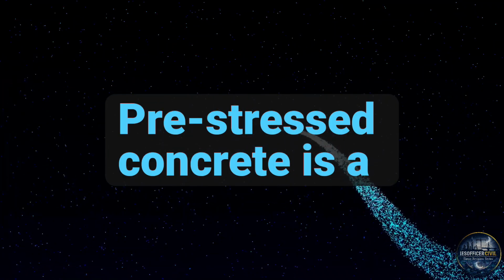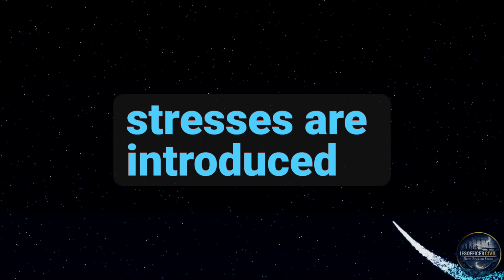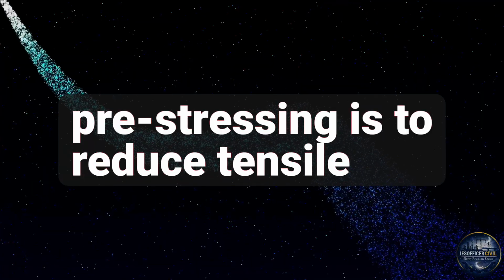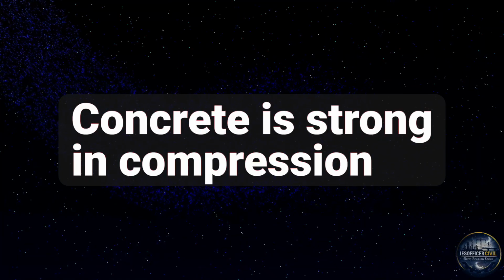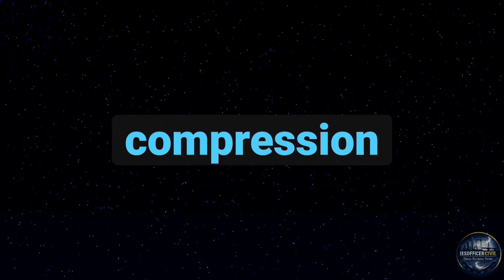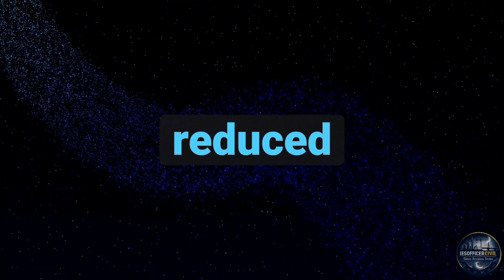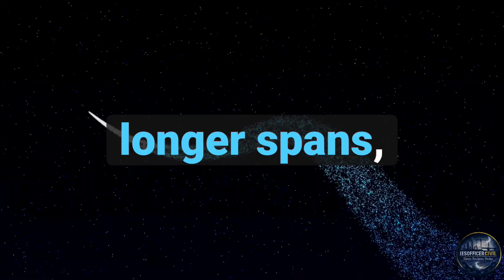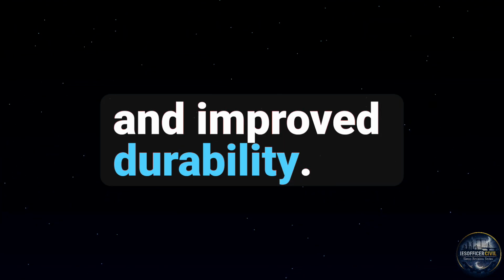Prestressed concrete is a special type of concrete in which internal compressive stresses are introduced before external loading. The main objective of prestressing is to reduce tensile stresses and prevent cracking. Concrete is strong in compression but weak in tension. Prestressing introduces compression so that tensile stresses produced during loading are reduced or eliminated. Prestressed concrete allows longer spans, smaller deflection, lighter sections, and improved durability.